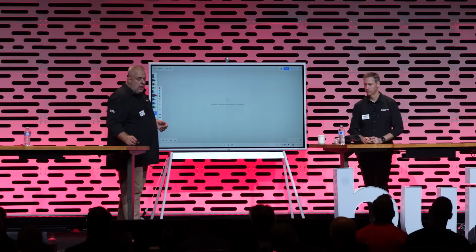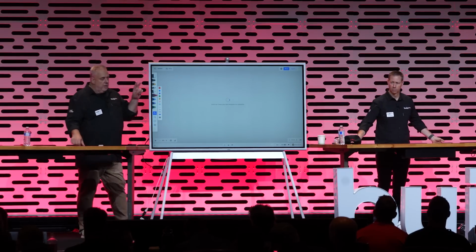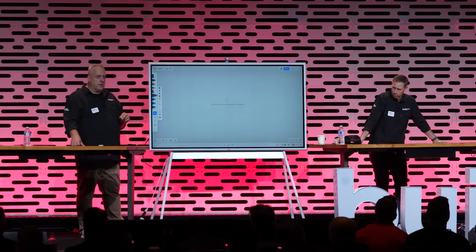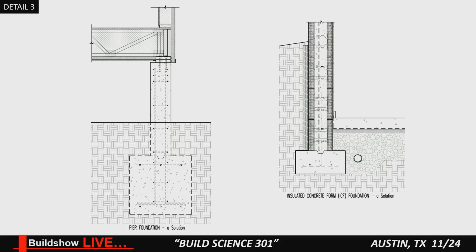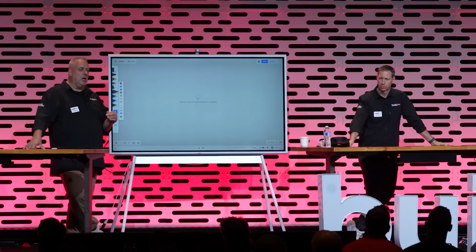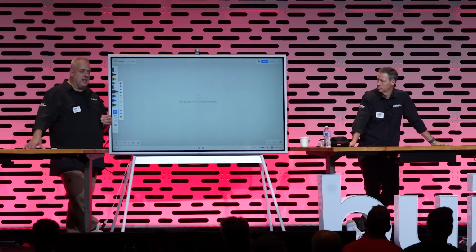When I go back and I look at that, notice the insulation job on that floor is 2 parts, right? There's the cavity insulation, that's going to take care of a whole bunch. But notice there's a ZIP R9 panel on the bottom. The reason for that is because you ask the question of, okay, we fill the cavity, do we have any thermal breaks across that system? Yeah, every time there's a truss. How do we battle that? We need to install insulation somewhere between the outside and the inside that breaks that truss from contact. So we put the ZIP R9.